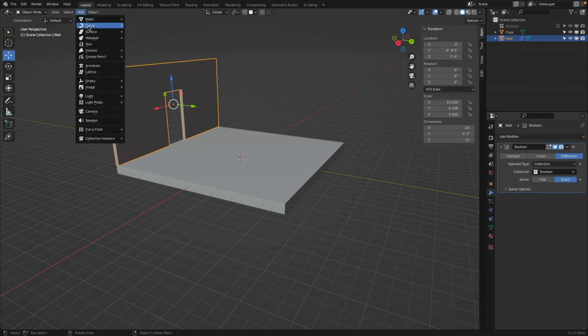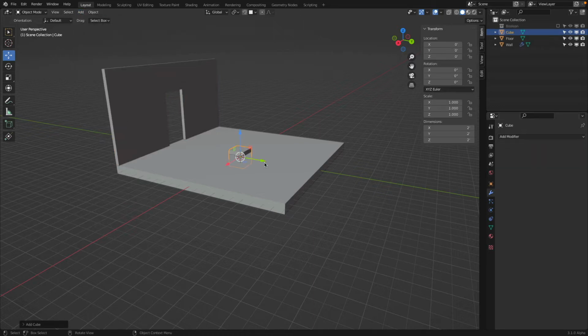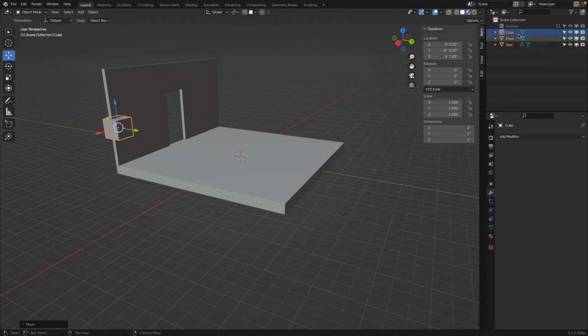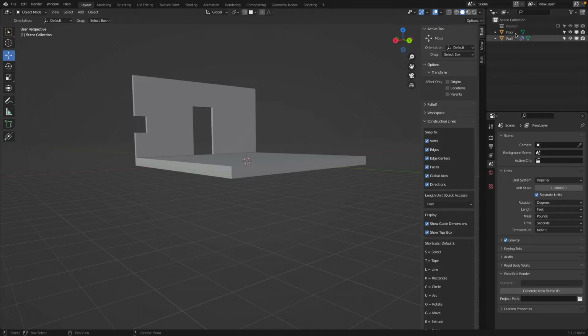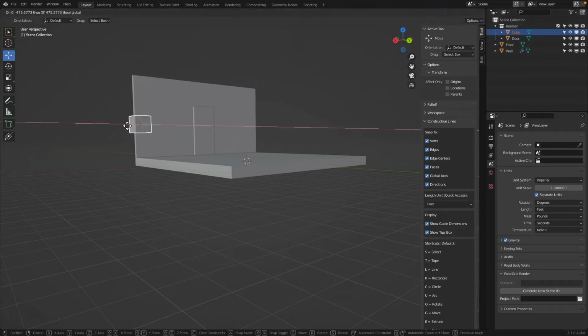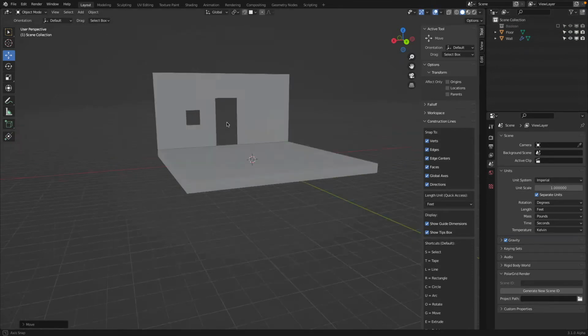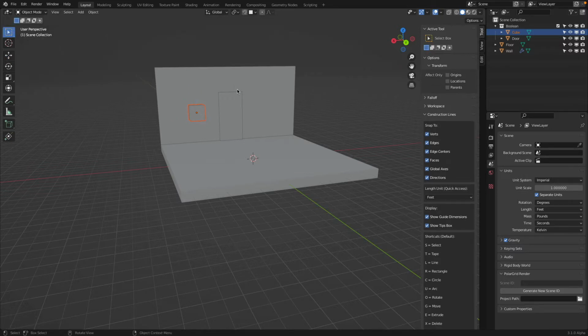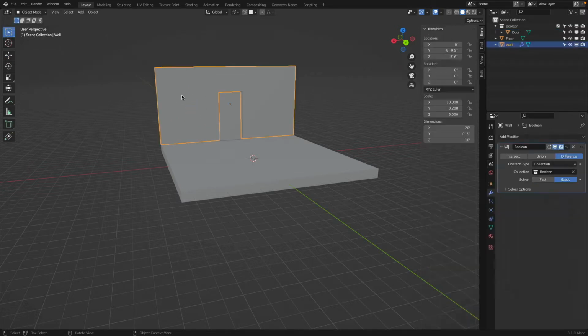Here another fun exercise. We can do another cube. I'm just goofing around right now. Where is it? There, it penetrates it. Very good. And now I drag this one in there. Zack, and you see, there is the hole. The cool thing is now if I move this object to somewhere else, it automatically updates this hole. So there's no manual cutting holes and moving holes. Okay, so X and delete.